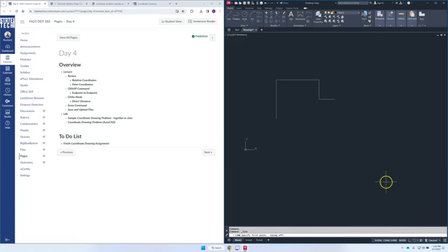But if you look in the bottom right-hand corner, right next to that right angle box, there is a square with an orange square in the top left corner. And if you hover it, it'll actually say Object Snap. So if I click on that, you'll see it highlights. And then if I hit the drop-down arrow right next to it, you can see a list of different snaps.